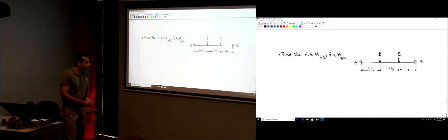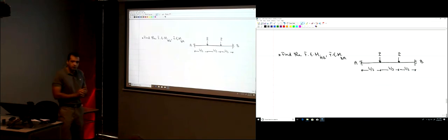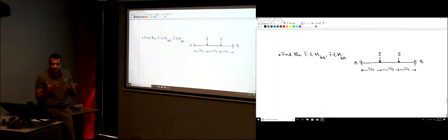Okay? So simple. It's easier than the last one that we solved. It's closer to the first two that we solved. What do I mean by this? It's symmetric. Okay, I'm helping you here. This beam is symmetric. So simply MA and MB are equal to each other.